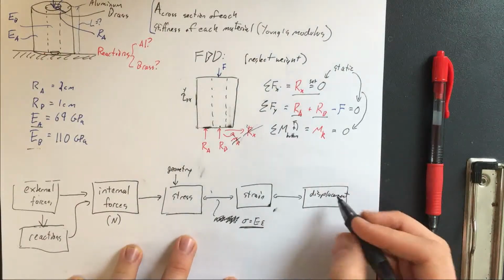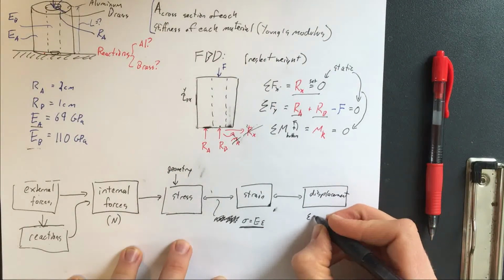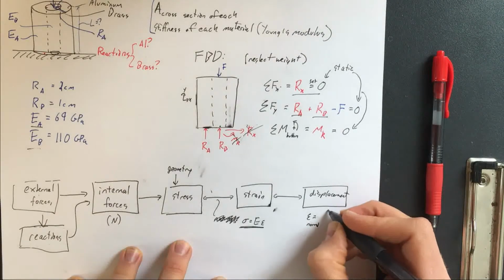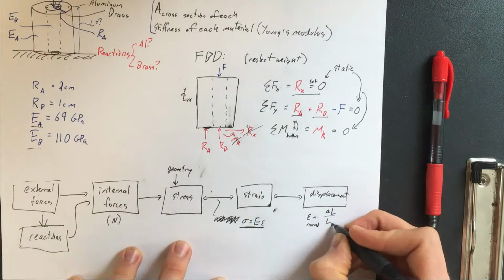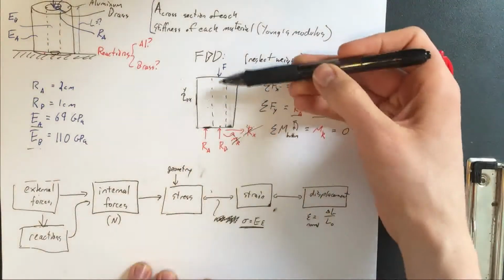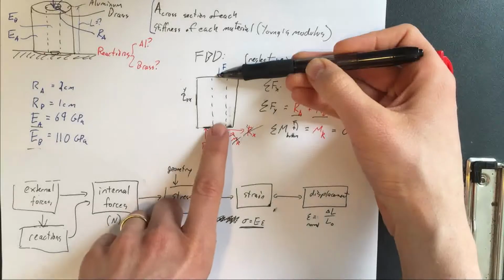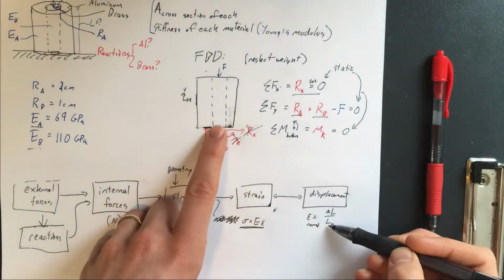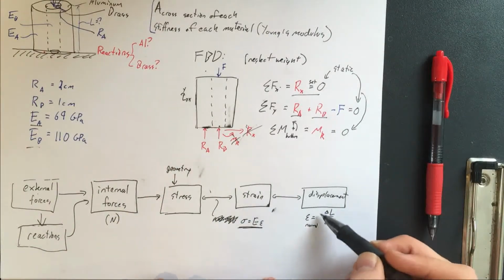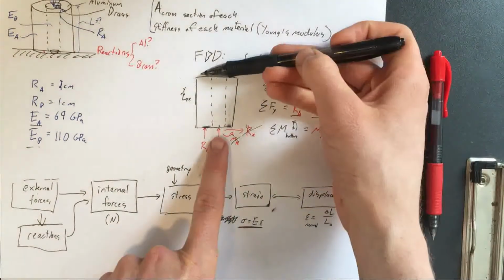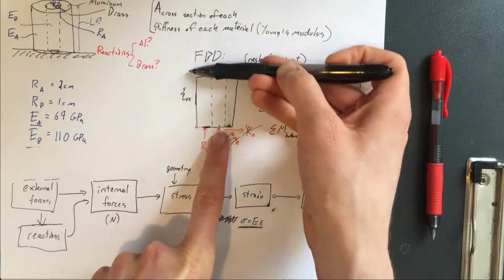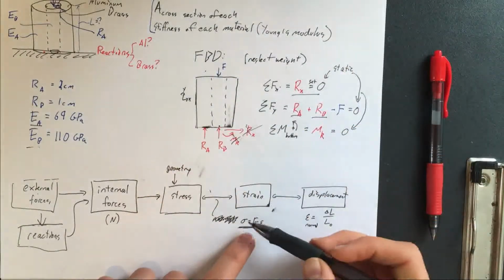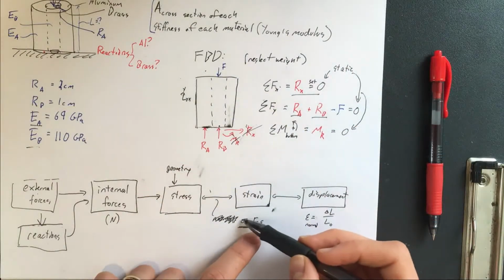For some problems, we'll need to relate strain to displacement. So normal strain would be equal to the change in length of something divided by the original length of something. So, hey, if these beams are deforming, if we're stretching them, the delta L's have got to be the same for both of them. The L naughts were the same, so we can relate strain to delta L's. For these things, if they're being squashed like this, the strains actually need to be equal to one another. We'll get there in just a sec. But that means the stresses might be different.